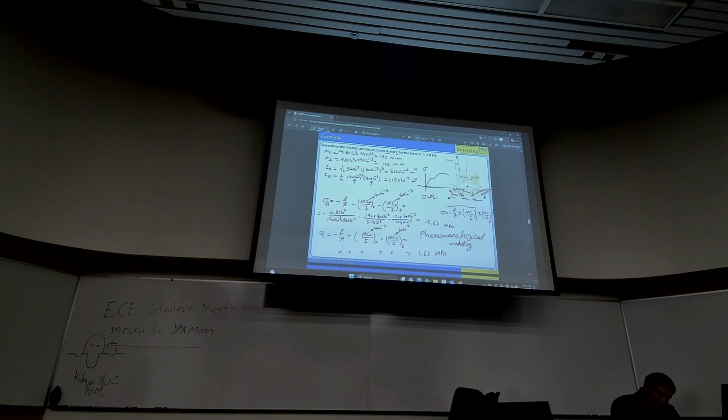This is sigma, this is epsilon. Sigma equals E epsilon works. And even in that region, if you zoom in on that region, that line is really not a line. It's really a combination of scattered data points. What people call a law, it's a misnomer. So how did those people, or let's say Hooke himself, come up with this equation?